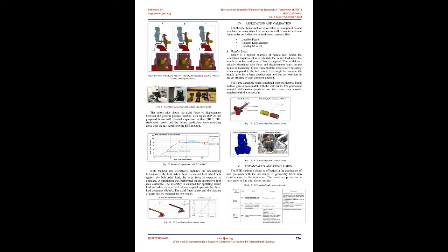If this condition is modeled using beams with rigid elements to the bolt face or with bonded contact, the sliding behavior of the bolt cannot be simulated. But with the thermal expansion method, the actual behavior of sliding was successfully captured, highlighted in red on Fig 5, in the simulation, and the same is observed during the test as well.